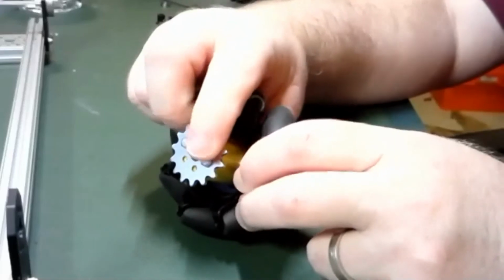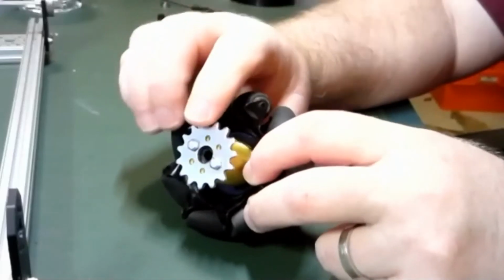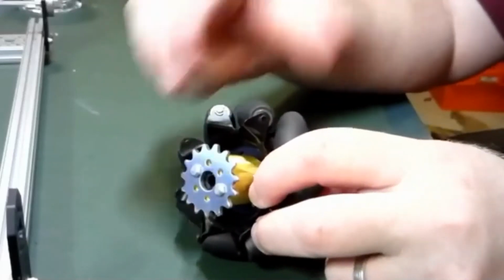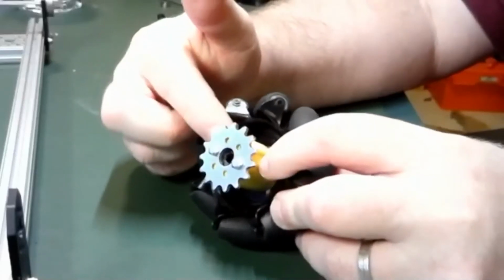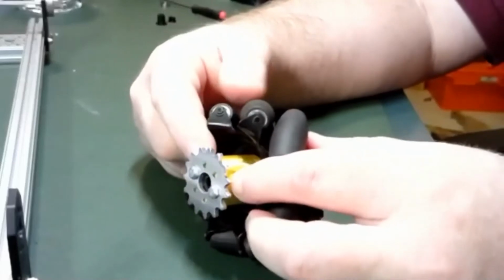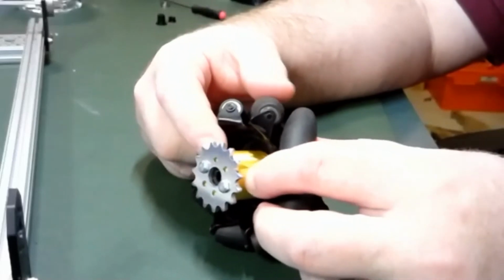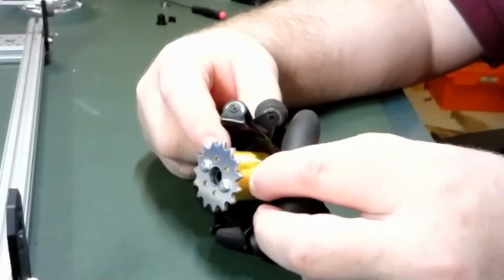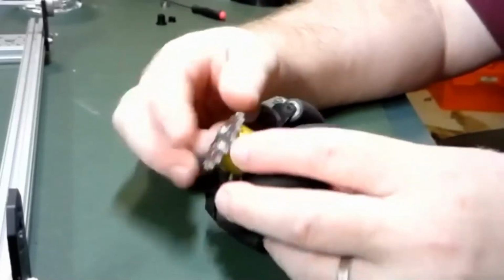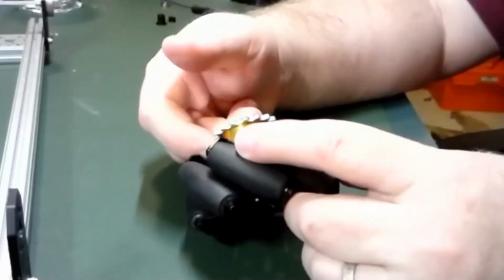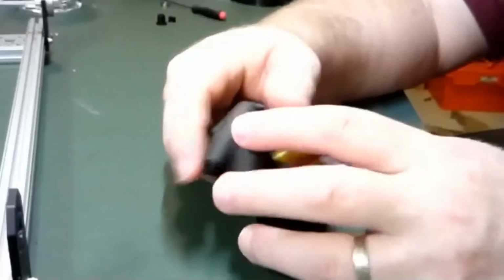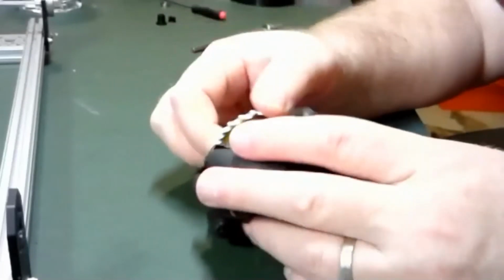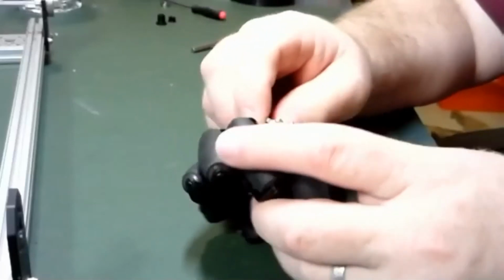And so the screws are the part that should be taking the bulk of the torque load that comes from spinning the wheels. So in this case, the 3D printed part is literally acting only as a spacer. It will carry some of the torque load, but not very much. And if you print it out of something like PLA Plus or a stronger plastic, I think it'll be strong enough. Can you use a dead axle with other wheels as well? Absolutely. That works just fine.